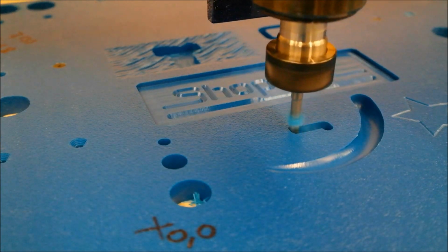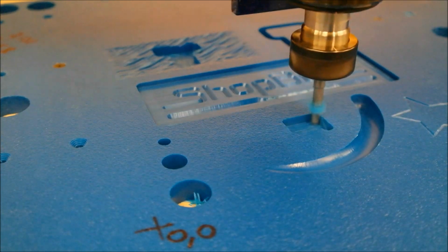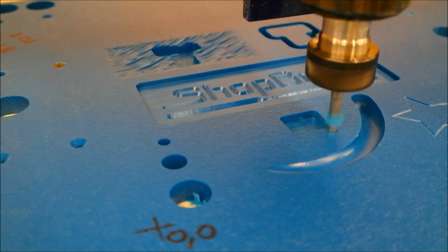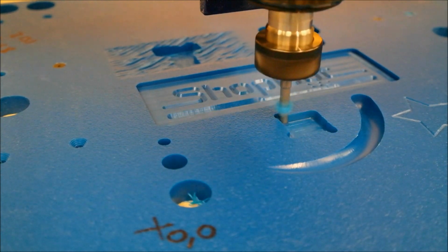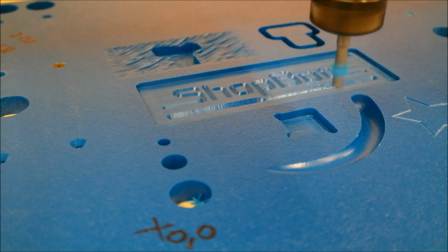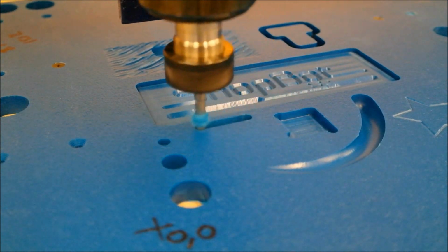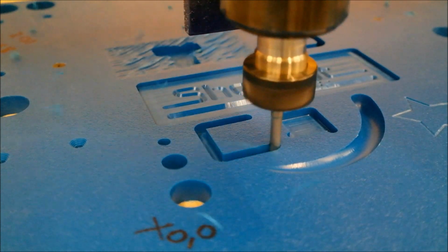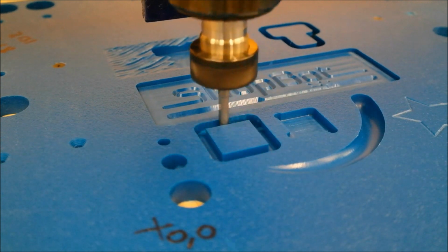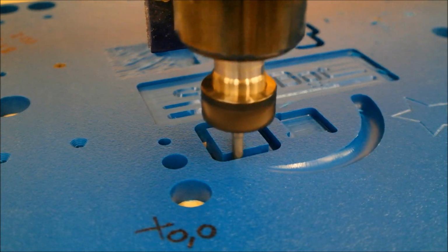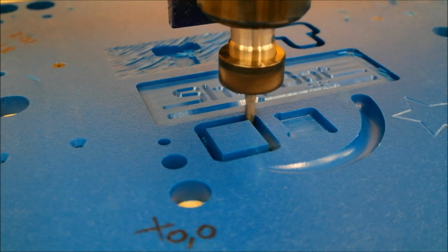Quarter inch bit comes down in, and it cuts out the dog bone or the T-bone depending on how it is that you drew them. So there you can see the dog bones, you can see the T-bones. There it is for the pocket portion, and then here is our actual square. We can keep the square corners right here on this profile cut.